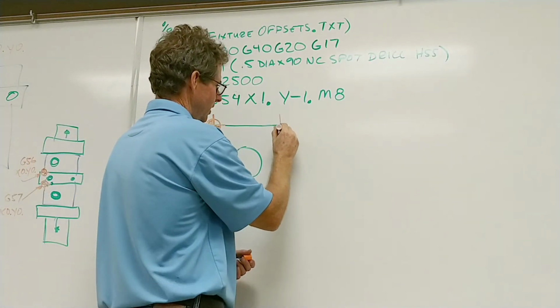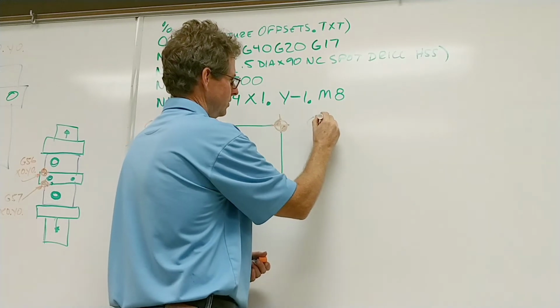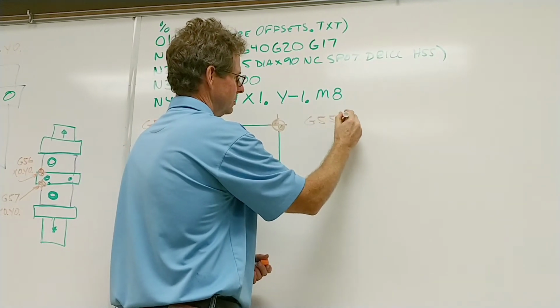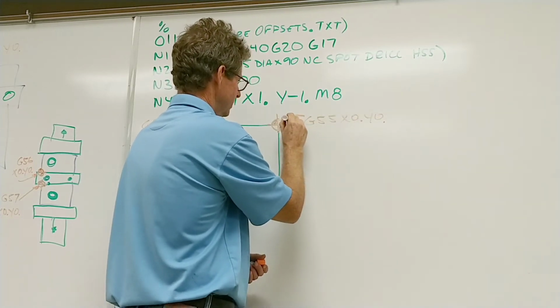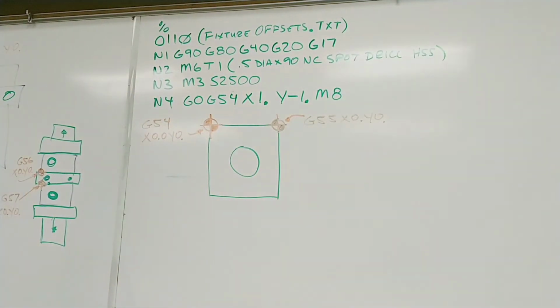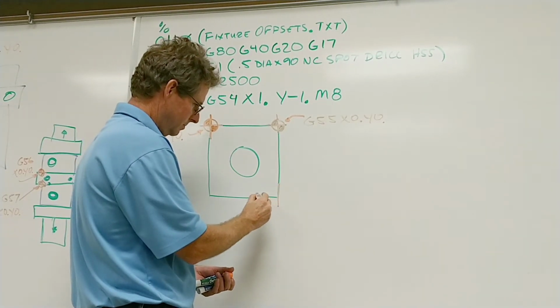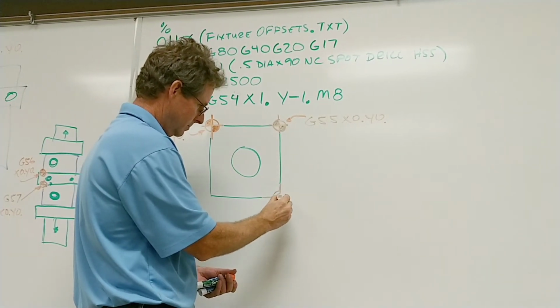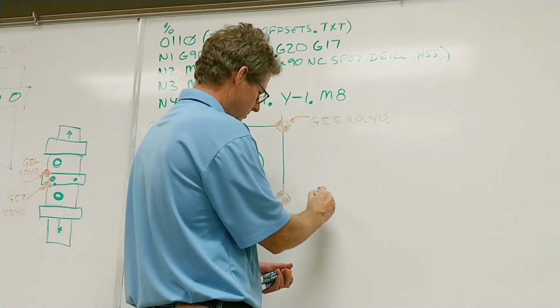On this upper right corner, we're going to set a G55 position. On this lower right corner, we're going to set G56.